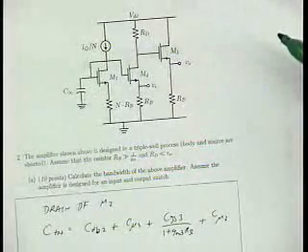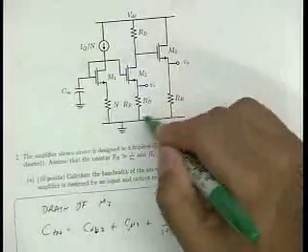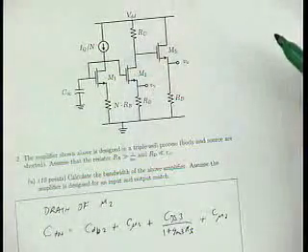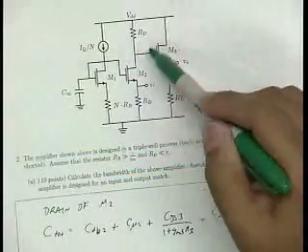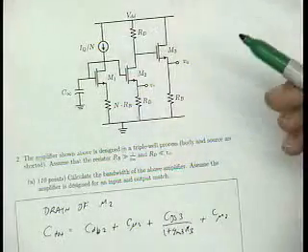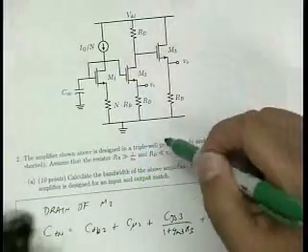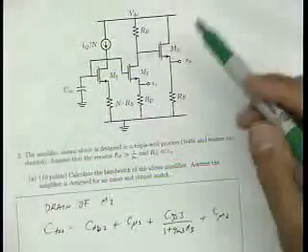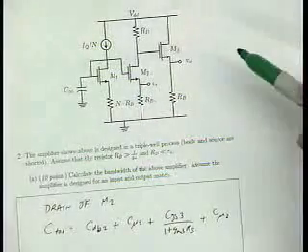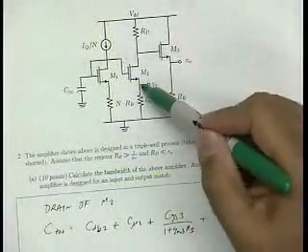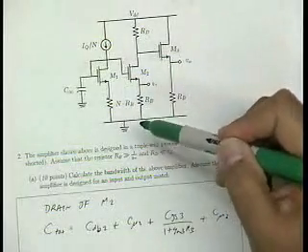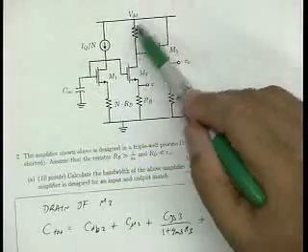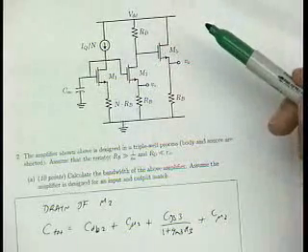So it's a 2-stage amplifier, and you're told that this resistance RB is much bigger than 1 over GM of this device, and RD is much smaller than the output resistance. Now, these are two big hints. It's saying when you do your analysis, make some nice simplifying assumptions. Forget about RO of this transistor, right? And the RO is actually going to be even larger because of RB, right? So it's a very good assumption to neglect RO of M2 and just assume that RD loads the drain.